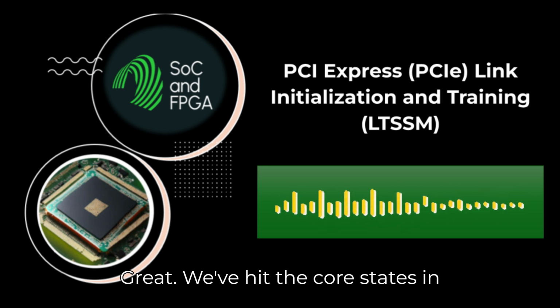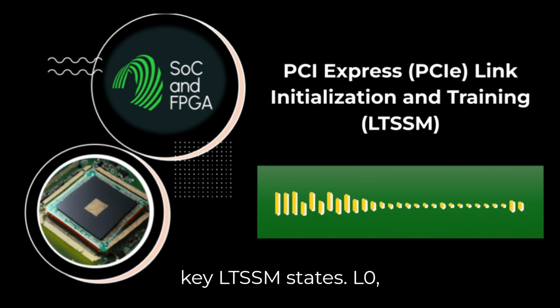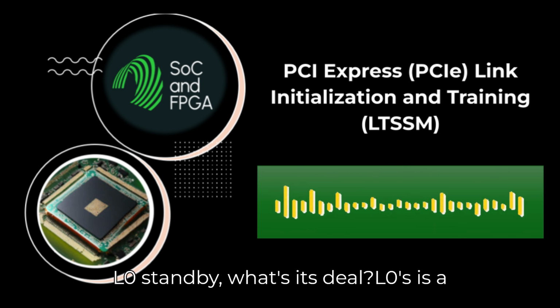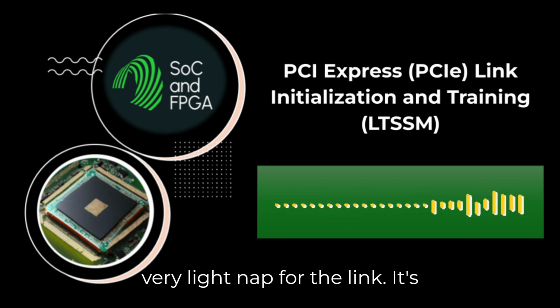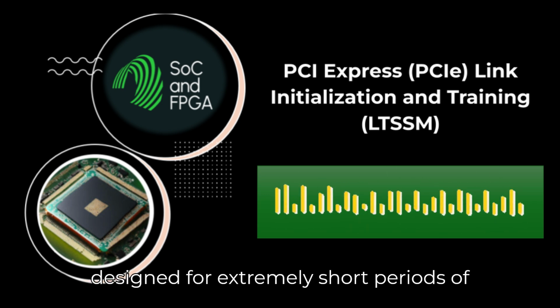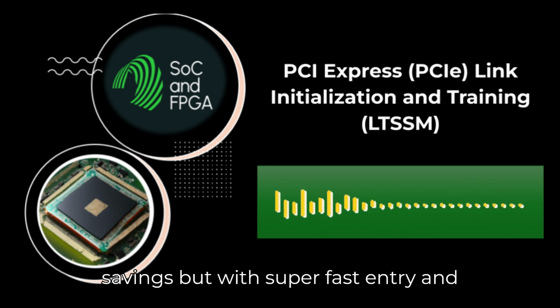We've hit the core states and recovery. Let's explore some of the other key LTSSM states. L0s, L0 standby. What's its deal? L0s is an optional state. Think of it as a very, very light nap for the link. It's designed for extremely short periods of inactivity, offering minimal power savings, but with super fast entry and exit.